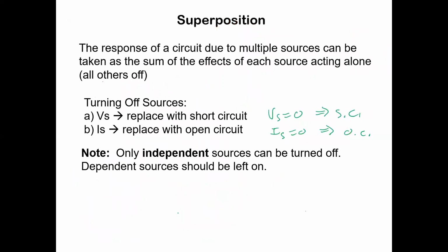Unfortunately, you can only do this with independent sources. Dependent sources have to be left on and in the circuit because they are responsible for something. You know, they're responding to some other part or some other variable in the circuit. You cannot leave those off. They always have to be on.